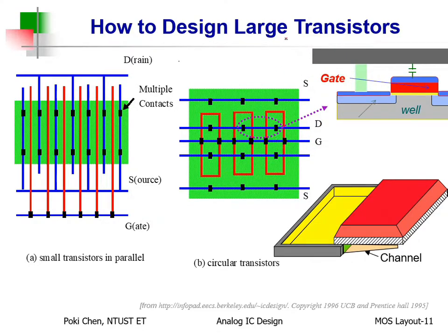According to what I explained already, if you can reduce the parasitic here, you can achieve much higher operation frequency. Okay? So to reduce it means what? You need to push it upward. Right? Don't use metal one for connection.